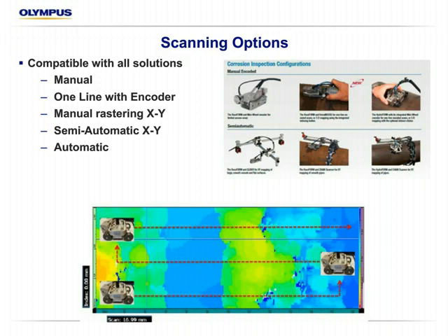And then we have more dedicated scanners, so link-based scanners for piping systems as well. Those are typically semi-automatic, in that an operator will drive the scanner around the pipe and then use the indexing features to move it over a certain set index and then scan around again until the entire area is scanned.